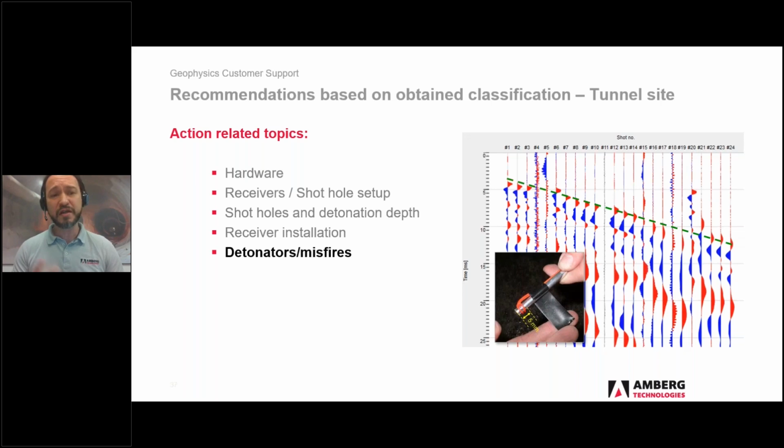If you are using non-electrical detonators with the wire break, you need to ensure that this wire break cable is always in this position. It's not like one time it is here, one time here, one time here. This will cause this variation in the first break time arrivals.